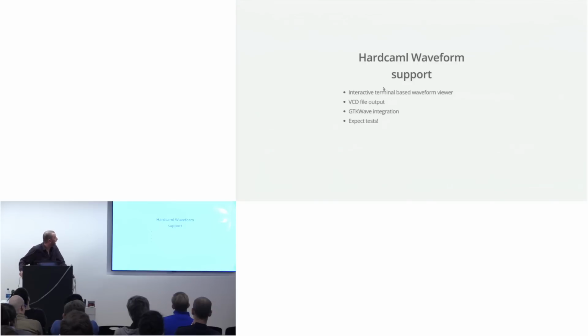So the support we have in HardCaml, there's an interactive terminal-based waveform viewer with scroll bars and the whole shebang that I actually do use a lot for debugging stuff. But if you want to, it can output VCD files, which are standard Verilog waveform files, and they work with any waveform viewer in particular. GTK-Wave, which is an open source waveform viewer, it's actually pretty good.